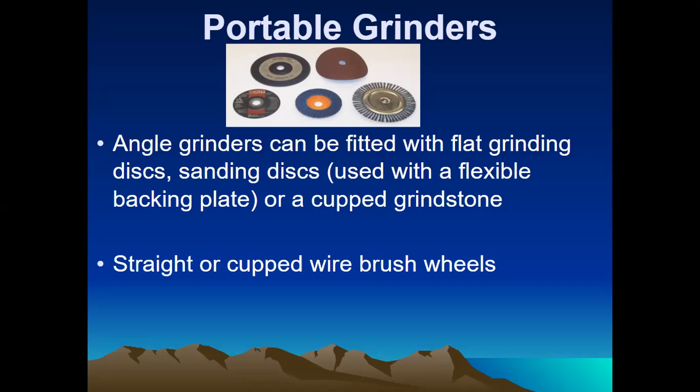When those wheels start to go bad, those little wire needles will break off and they'll go flying. So it's often a good idea to be wearing something like a welding jacket in the shop when you are grinding, because those needles will embed themselves in something like a grinding or a welding jacket. Or if you're not wearing that, could be in your t-shirt, could be in your stomach, could be in the front of your thighs. Every now and then when using these, I do find a needle sticking out of my jacket or a shirt or something like that. They just get tossed off as those wheels start to wear. But that is why we wear things like face protection.